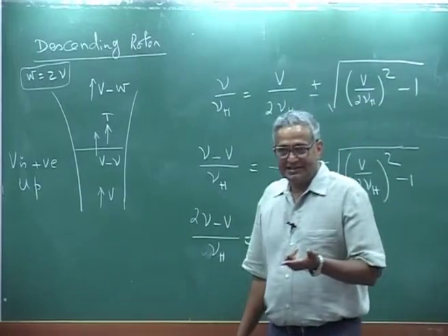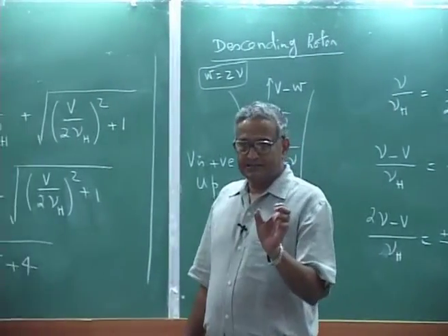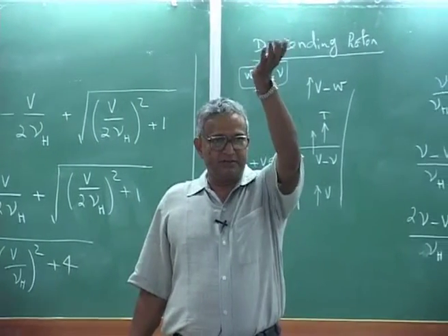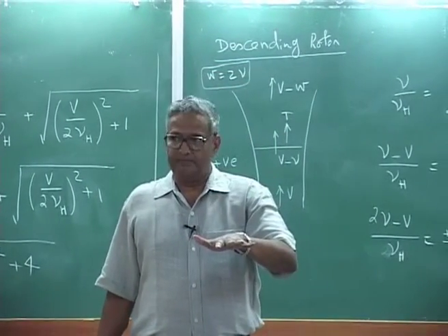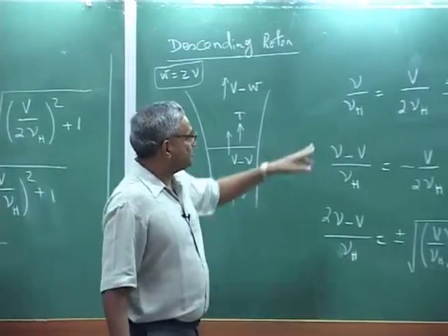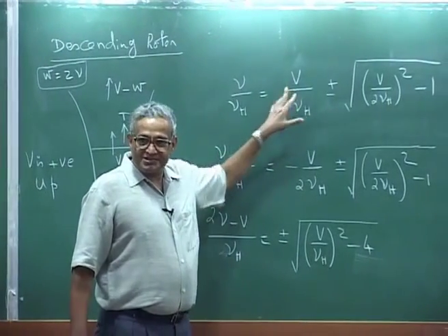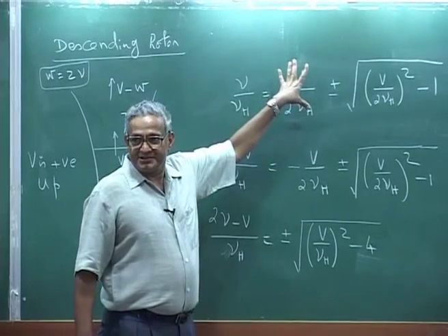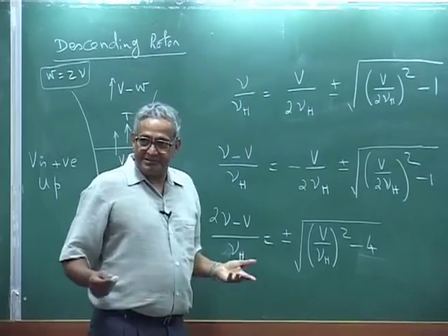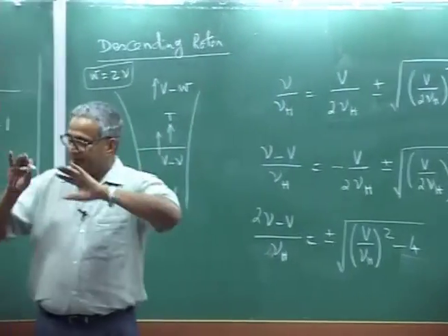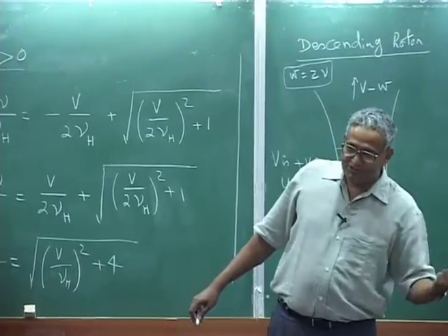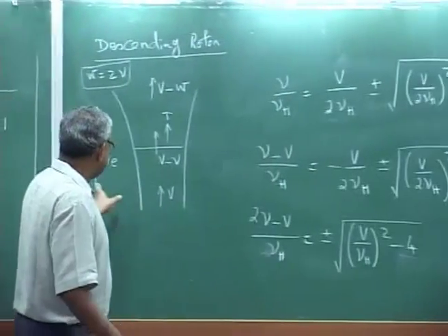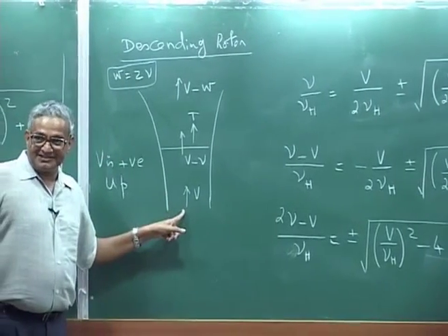On the other hand, if I want to call my velocity positive when the helicopter is going up and negative when coming down, then in these expressions I can just change the sign of purely the velocity. If I change the sign, then when I use descent I have to put minus V, not plus V as is marked here.